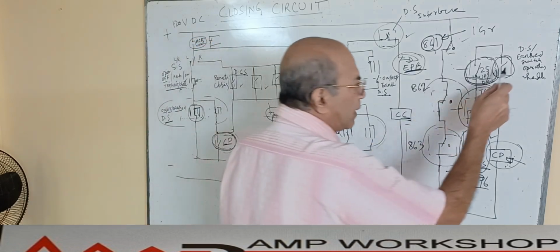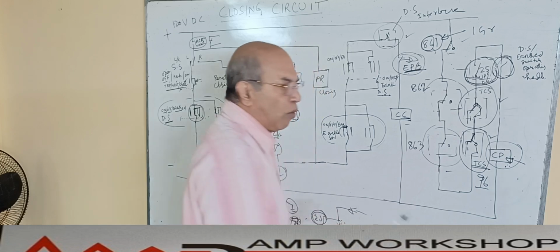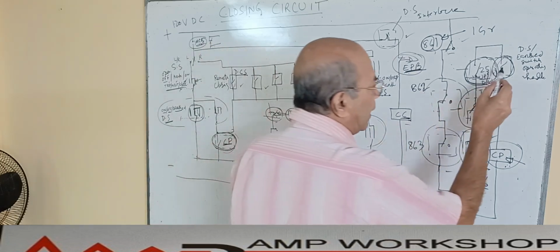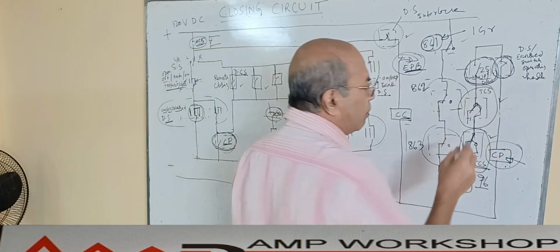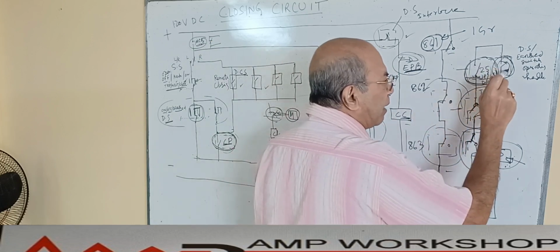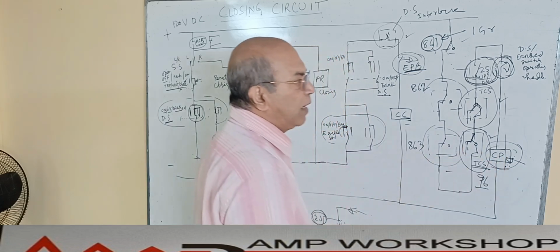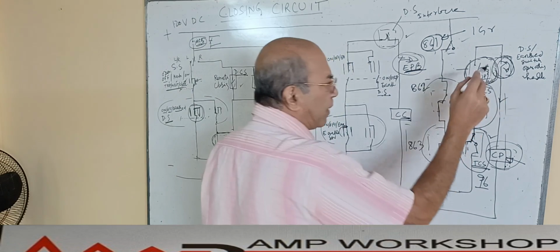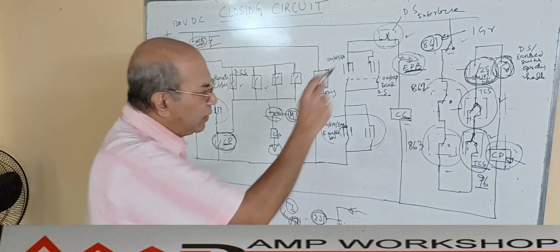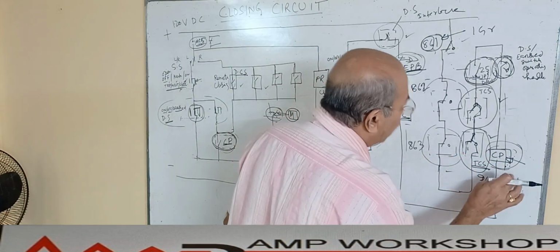So this is another interlock which makes sure the operating handle is not inserted. This contact is normally NC; the moment I insert the operating handle, it becomes NO, and it will not flow the power. So the closing permissive relay will not pick up. So this also makes sure the operating handle is not in position. With these three interlocks, we will get the close permissive.